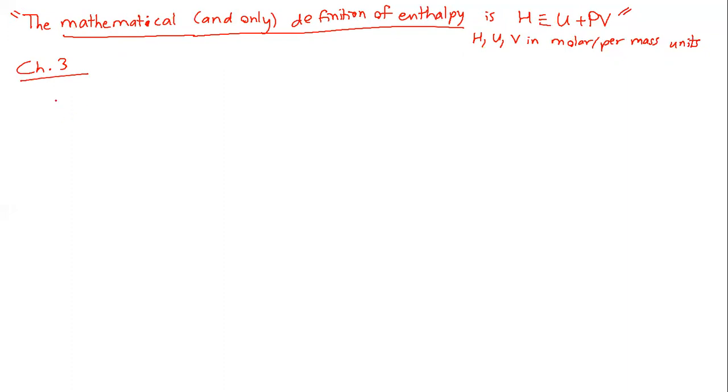This is about the volumetric properties of fluids. In this chapter, there are a lot of things about different equations of state. It is important to remember your equations of state and to go over your different thermodynamic relationships when you're trying to choose your property method in Aspen Plus, because each of them has benefits and limitations.